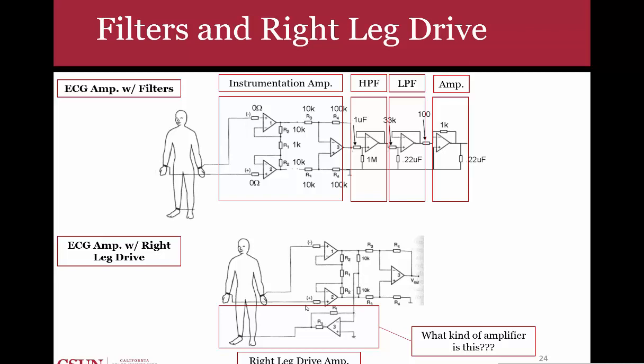You're going to get that signal, apply it onto an inverting amplifier, invert the common mode signal, and drive that signal back to the right leg. So what you're basically doing is creating a negative voltage of that common mode and putting it back into the person. Now the inverting amplifier allows you to attenuate that signal a little bit so that you're not zapping the person, but that's another way to eliminate it. What you're actually doing is pumping back in charge to effectively eliminate any charges or any other noise that's impinging on these two electrodes here. And it actually works fairly well.